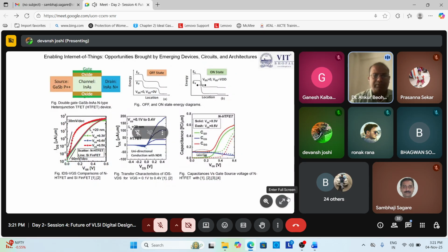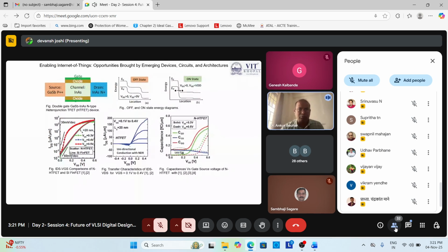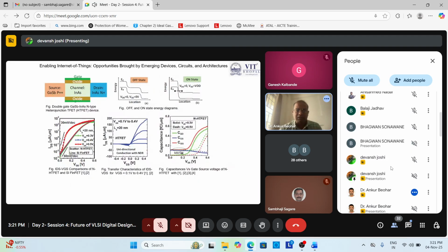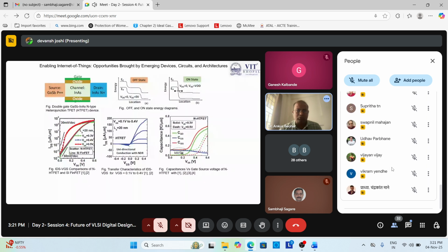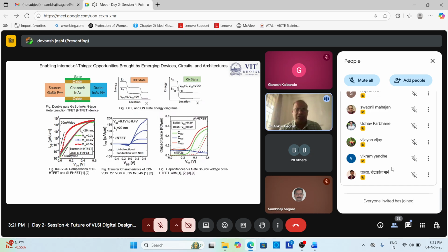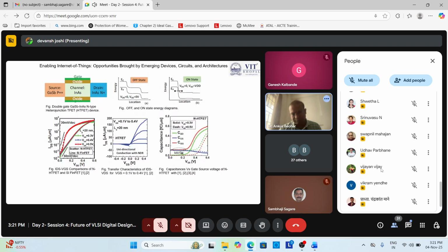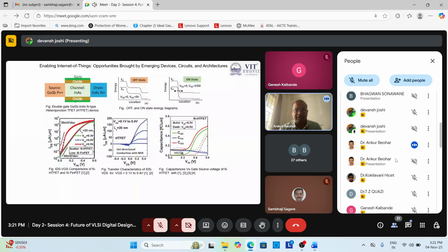They have optimized and replaced the conventional silicon, germanium, silicon germanium compounds and gallium arsenide with gallium antimonide. Due to the optimized band gap property of this compound material, it allows more charge carriers to flow between the valence band and the conduction band. In this way we are getting a subthreshold swing as low as 30 millivolts per decade, which is a great achievement.